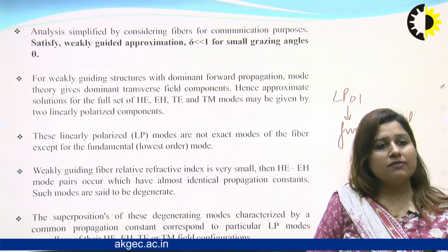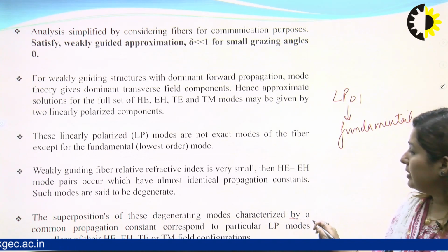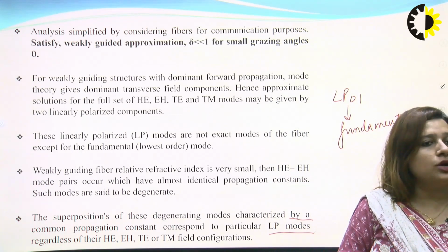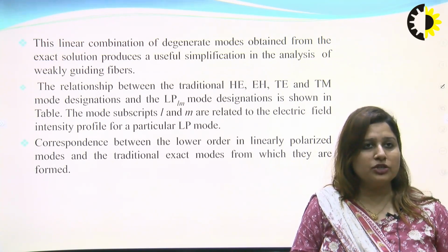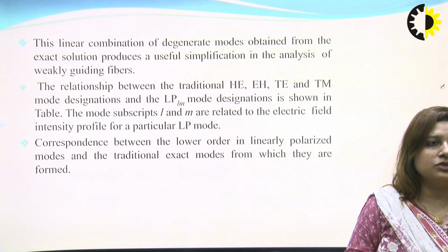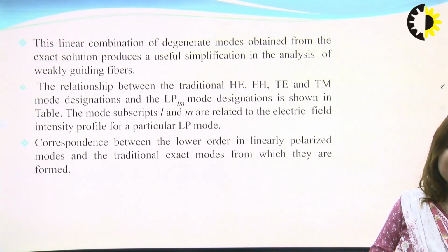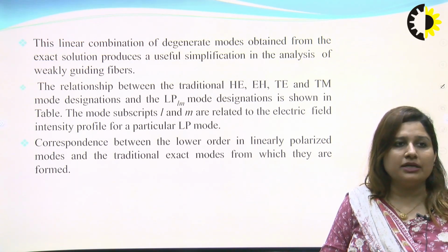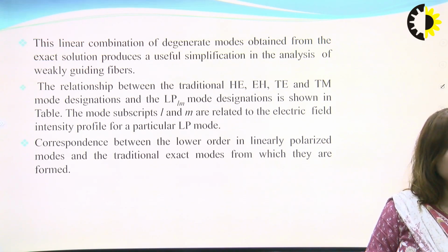So, the superposition of these degenerate modes is characterized by a common propagation constant corresponding to a particular LP mode, regardless of their HE, EH, TE or TM field configuration. This linear combination of the degenerate modes obtained from the exact solution provides a useful simplification in the analysis of weakly guiding fibers. The relationship between the traditional HE, EH, TE and TM mode designations and the LP-LM mode designation is shown in the table. In the next slide, we will discuss the table, how the HE, EH, TE and TM modes are designated.